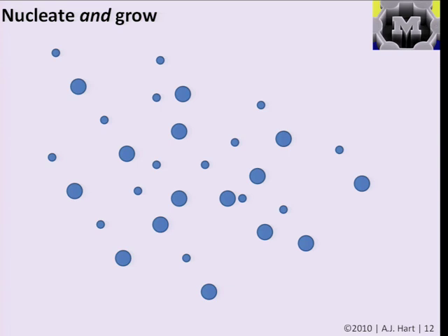But there's an important difference whether I can control my process. So I nucleate and then I grow, where maybe in the first step I only nucleate, and in the second step I grow some of the initial nuclei bigger, but I form additional nuclei. And you can see here, now I'm starting to get, in this case two distinct sizes, but really I'd have a broad size distribution, a case where if I am simultaneously creating new structures and making older nuclei bigger, I lose control pretty quickly.